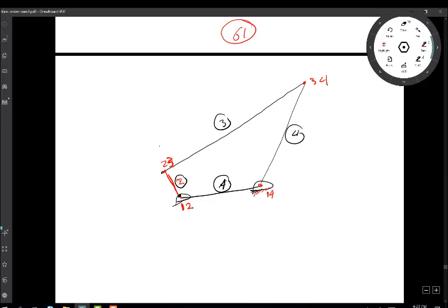Now, if I want to find 1, 3, I realize from this end I have 3, 4 and 1, 4. Common number is 4. The missing point is 1, 3. So I extend this link here. I know that's a locus for 1, 3.